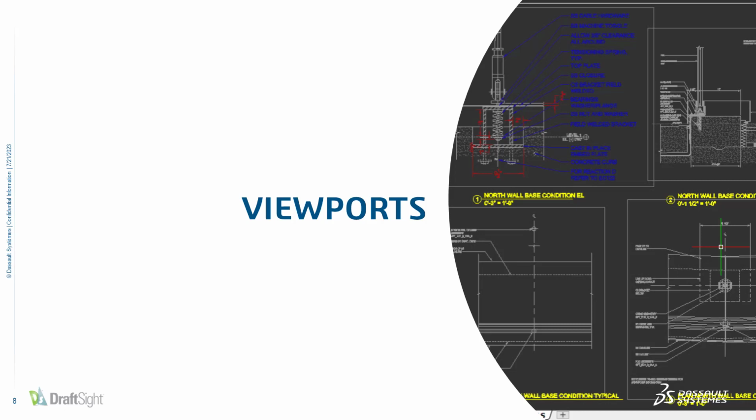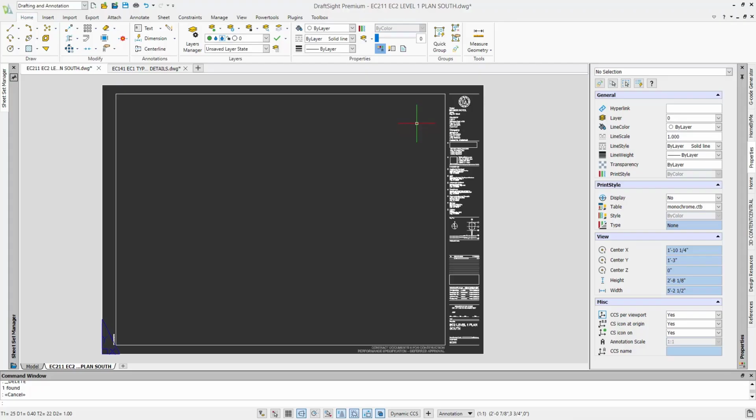The quick benefit is to be able to draw things true to scale and then easily scale them down to fit properly onto an actual piece of paper without having to redraw or rescale the actual model that has been drawn. So I'm going to open DraftSight Backup to show a few examples, one being how to create different types of viewports, and then additionally, what situations would you use multiple viewports on the same drawing file.